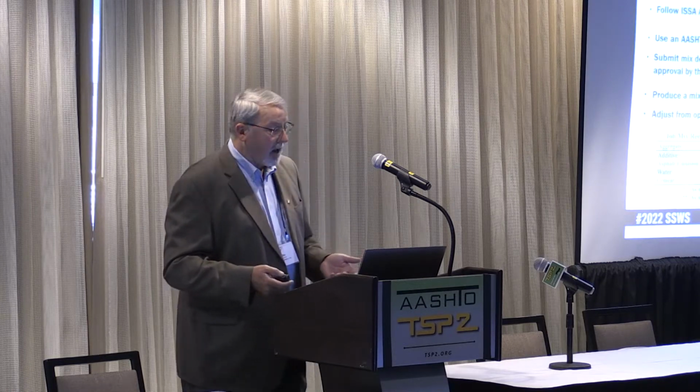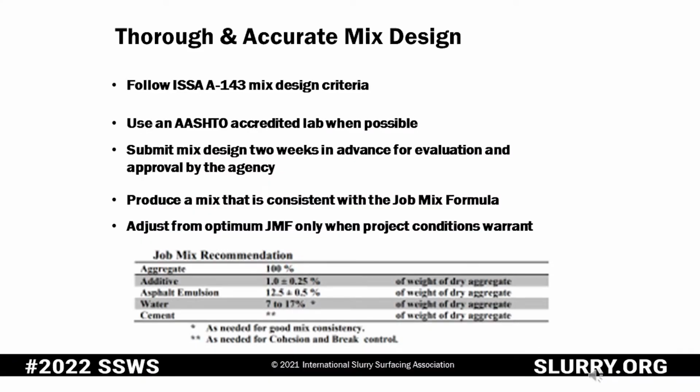Thorough and accurate mix designs. Obviously, we want to follow the ISSA A143 mix design criteria, use an AASHTO accredited lab when possible, which is becoming more and more possible as the days go by.